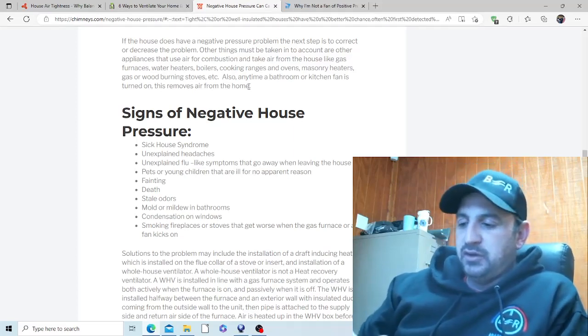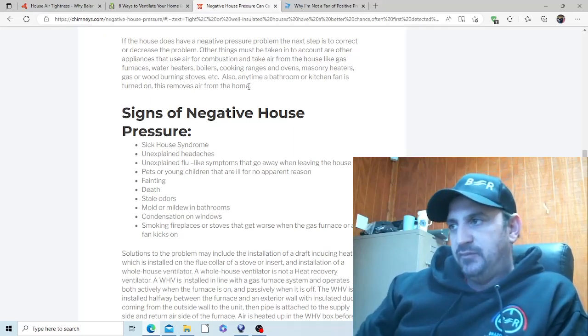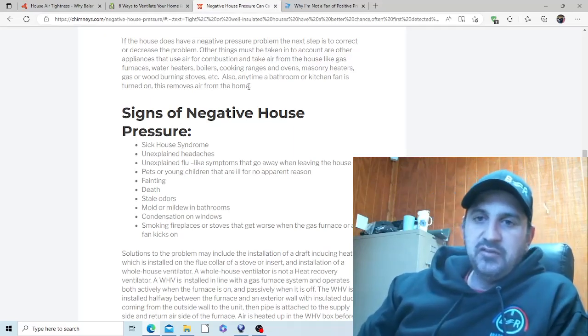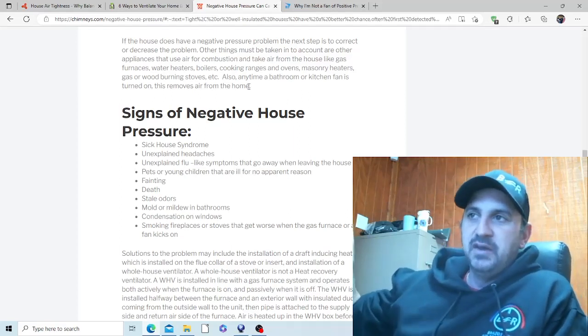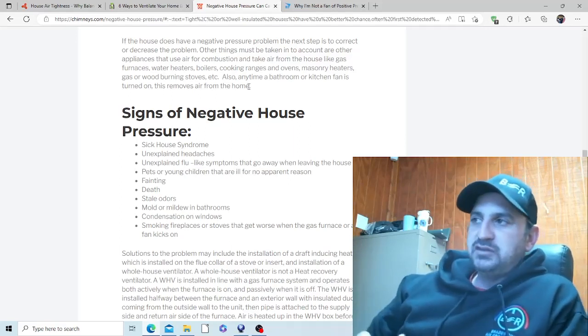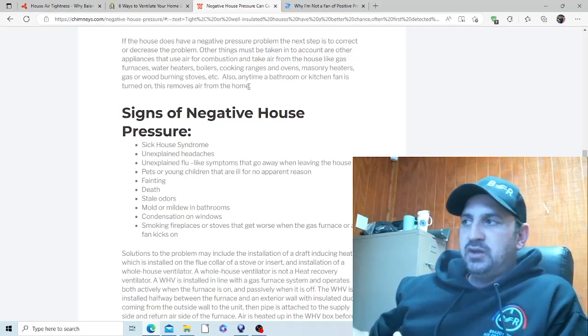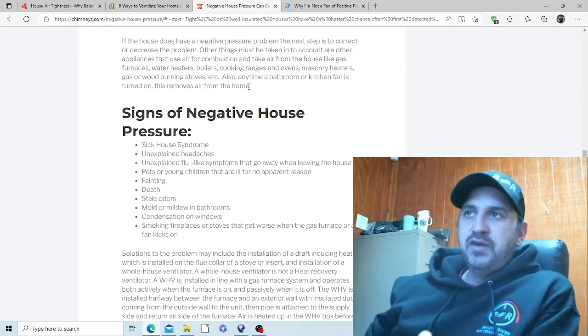You have your kitchen vent fans, your bathroom vent fans, and your attic vent fans. All of these are taking air and removing it and sending it outside. When they send it outside and there's no air being pulled in, it pulls your house into a negative pressure. By pulling it into a negative pressure, it's going to draw more in from the outside.